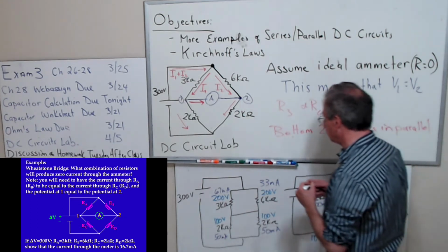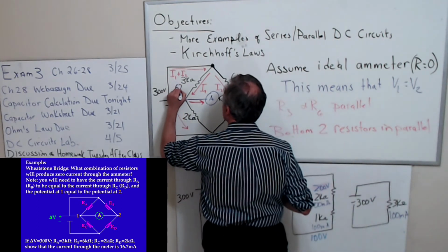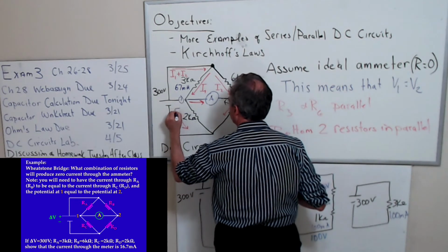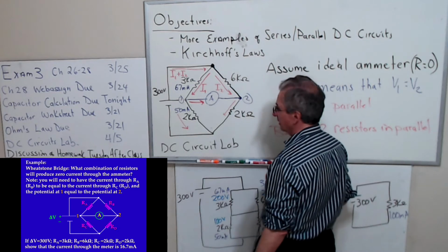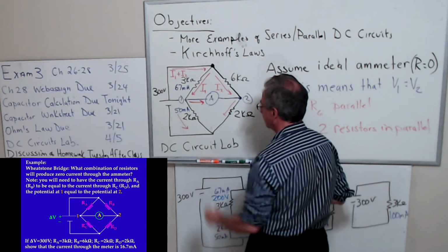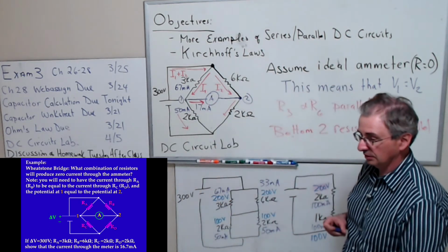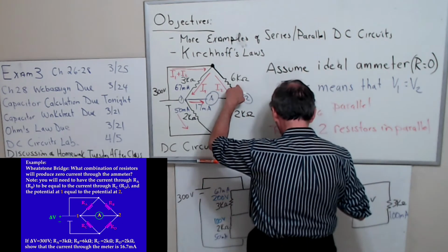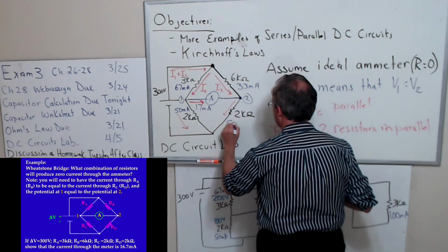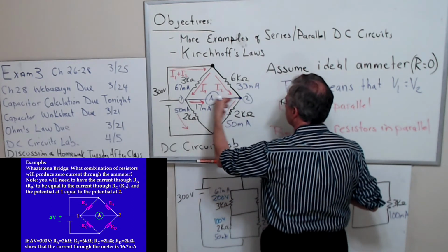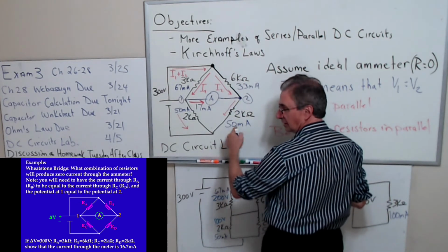Okay, so I have 67 milliamps here, 50 milliamps here. How much goes that way? What's left over? 17 milliamps. So 17 milliamps goes through the ammeter. Does it check? Well, let's see. This side was 33. This is 50. So you have 17 going this way, 33 going that way. What's 17 plus 33? 50. Okay, so it works out, right?